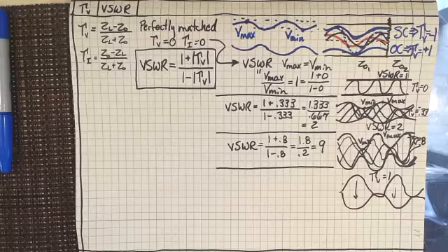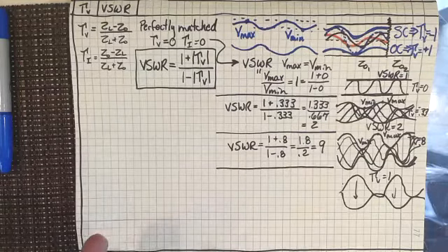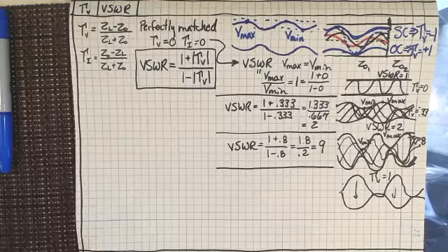And yes, you can have VSWR meters, and you can work toward it. You may have to change the antenna, maybe you have to change the line a little bit, you have to put a transformer in there, a variable transformer, so that you can match those two impedances. And you can do it by stub matching, and that's what I want to show you with the Smith charts at the very end of the course.